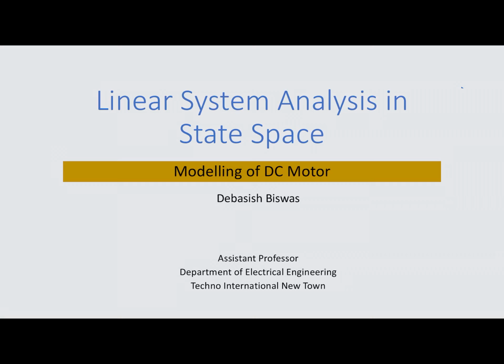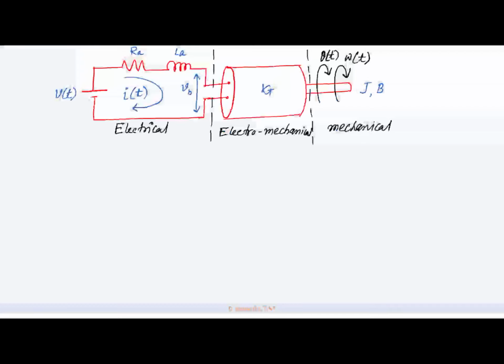Armature control DC motor is used as an actuator where position control and velocity control both are equally important. Considering the linear zone of operation, it has three different parts: electrical circuit, electromechanical circuit and mechanical circuit. In case of electrical circuit, the equation of dynamics can be written using KVL.